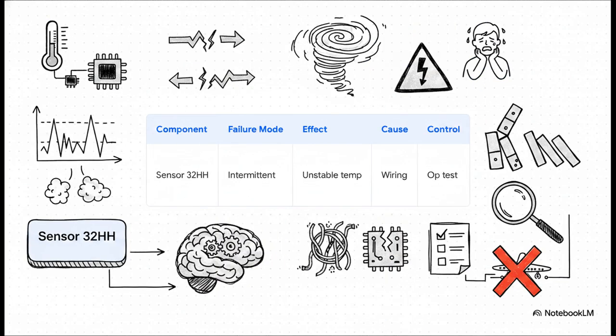And then there's suspect number 3, the pack temperature sensor. Its function is to monitor system temperatures and provide inputs directly to the system controllers. The failure mode is an intermittent fault. And guys, this is a big one.